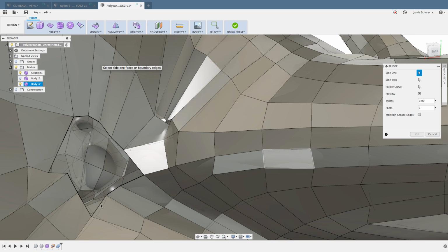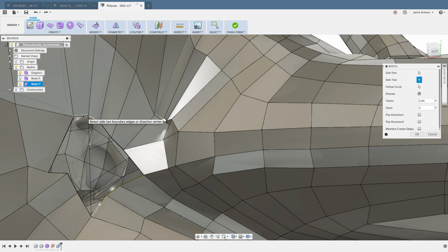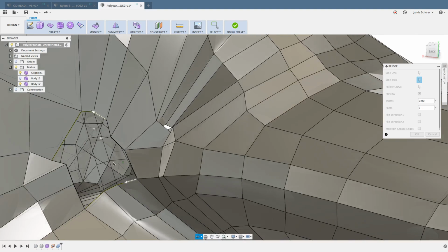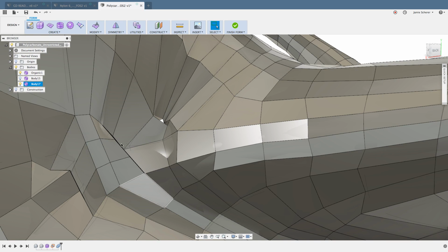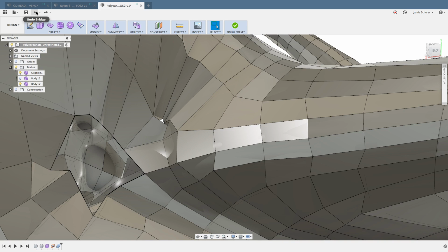So we'll do a bridge between 1, 2, 3 faces, and we'll bridge that on the other side over to these 1, 2, 3 faces. And again, I'm going to do a 3 face span so that they'll match up nicely with the others. And similar to what we did before, a little bit of repeating, but now I would just go through and re-weld them back together. The last quick example or workflow, I'm just going to undo this for now